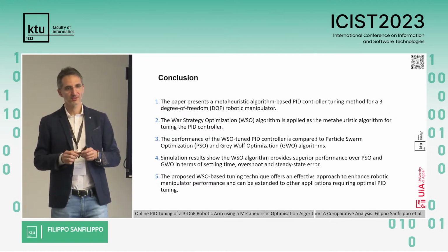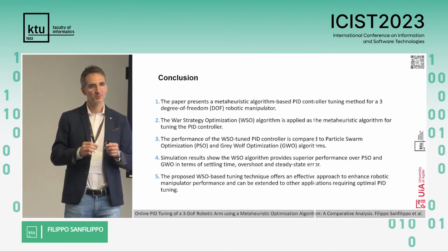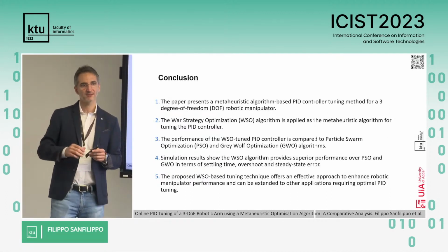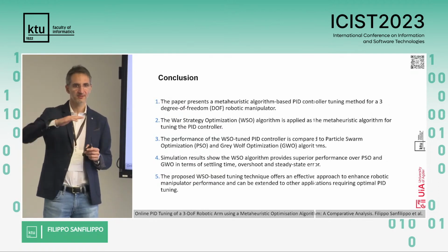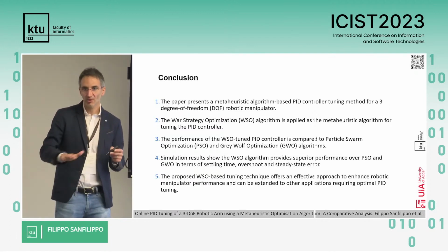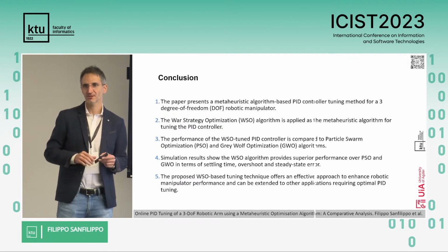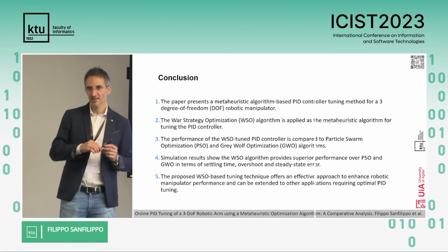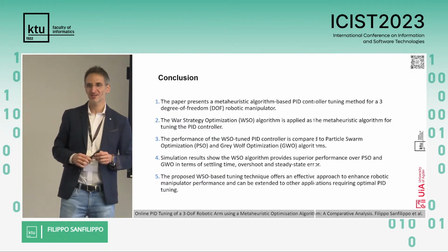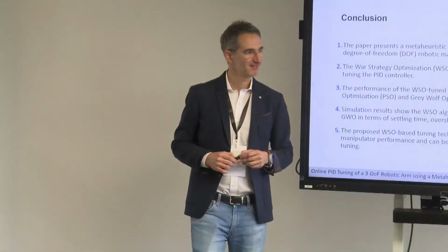This kind of robots today have reached this level of autonomy because of the combination of traditional control algorithms like PID controllers with more advanced AI-based algorithms built on top. So we have different layers of intelligence, but the bottom layer, the low level that is in contact with sensors and motors, is still based on traditional control algorithms like PID controllers. With this, I would like to conclude my presentation, and I'll be happy to answer your questions. Thank you very much for your presentation.